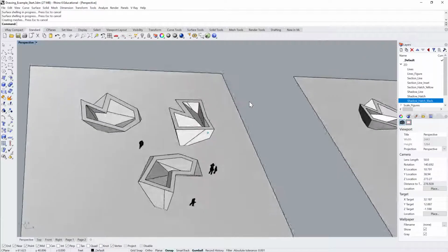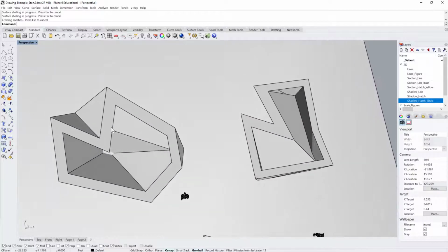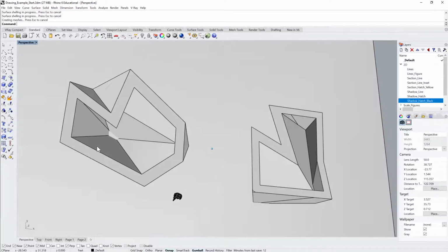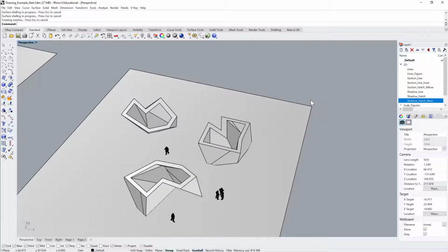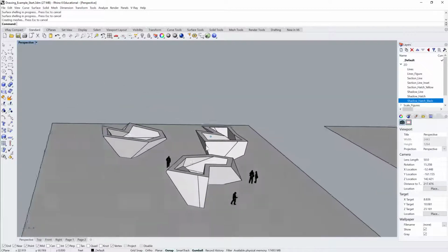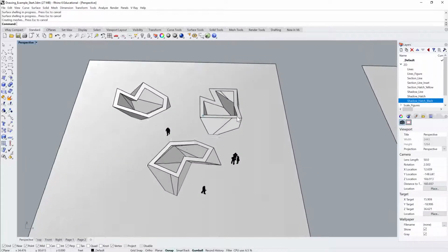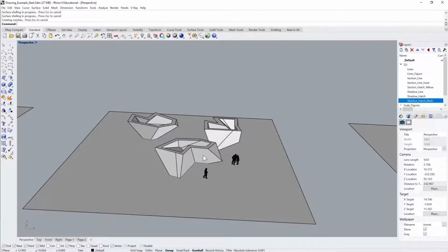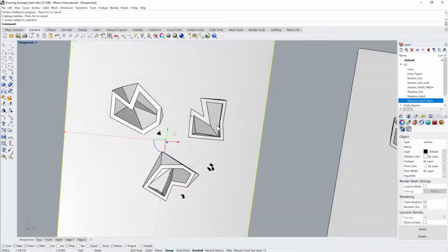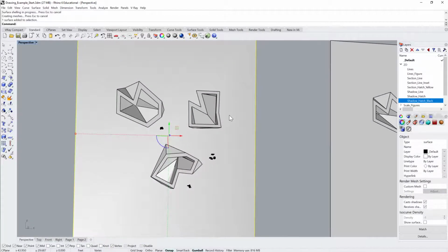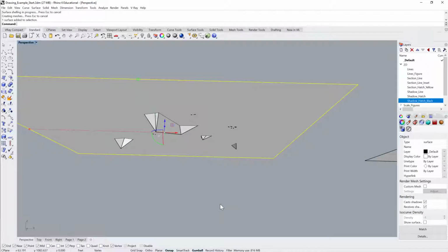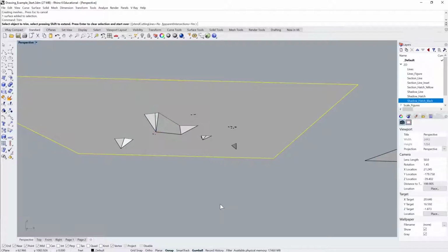Okay, great. Now I have these things properly offset, and you can see that we're getting a much better offset than we were when we offset the whole poly surface, or let's say inset the whole poly surface. So it's just easier for Rhino to calculate this. Okay, so before we run a make 2D operation on this, we would probably also take this plane and use it to trim anything that's poking through, so that we find the floor.